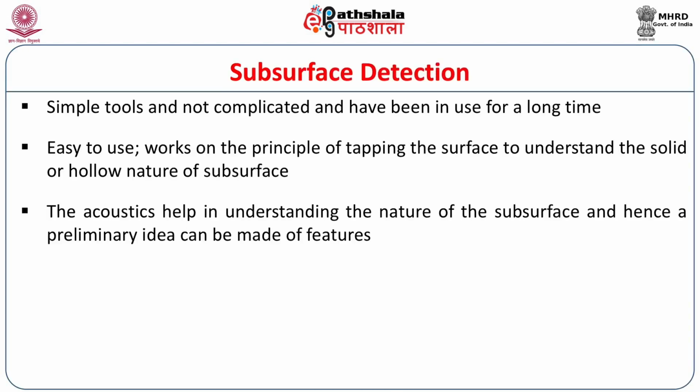If certain buried floors are there, the surface can be tapped and understood by listening to the nature of the sound. The acoustics principle used in this subsurface tapping helps in understanding the nature of the surface, and hence a preliminary idea can be obtained, and then other detailed scientific tools can be used to probe.